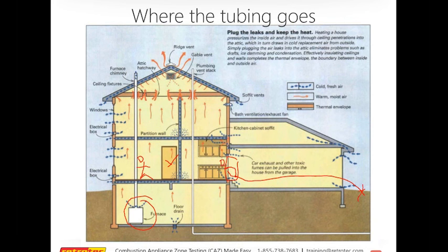So let's imagine that this is where the back door is. What if we set our fan up here? We set up our reference tube to the outside right here, and then we set up our gauge right here. And now let me see if I can get a different color. Okay, great. So I'm going to use my reference hose. We're going to reference red to blue because it's on the left, the A channel, right?